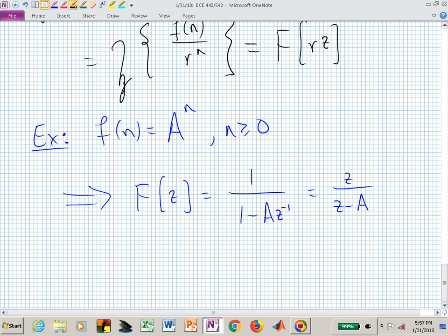What if somebody now said, I want you to find the z transform of g of n, where g of n is now f of n weighted by, or dividing by, r raised to the n. Plug in an r value, let's say of 2, and what's this doing? Now you're dividing by 2 to the 0, which is 1, 2 to the 1, which is 2, 4, 8, 16. You're chopping this f of n down more rapidly. It's decaying more quickly if little r was something like 2. So you're just exponentially weighting this original f of n by something a little bit more powerful.